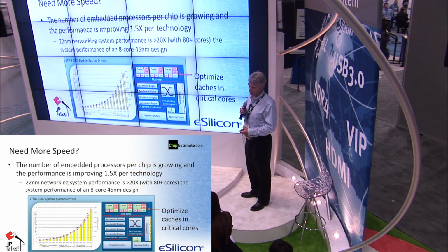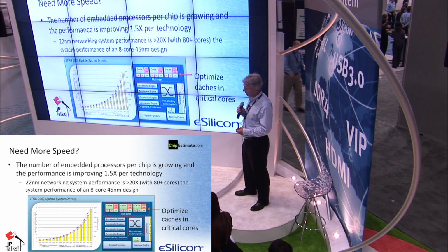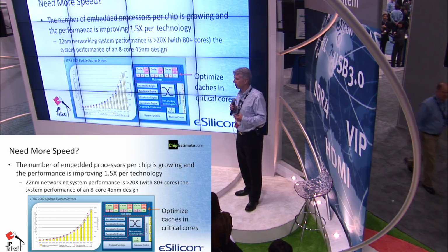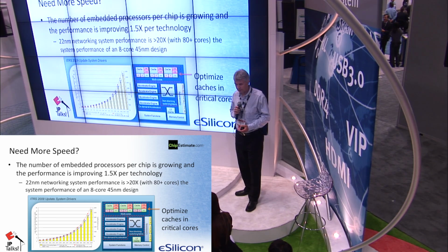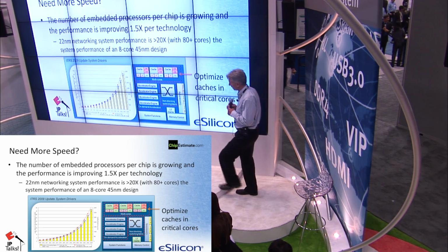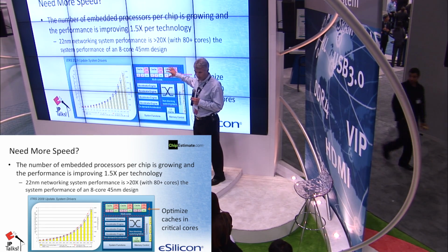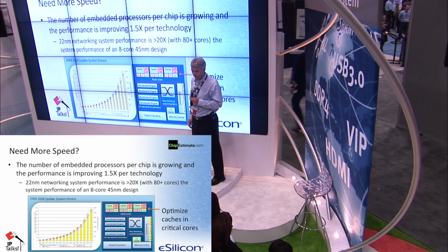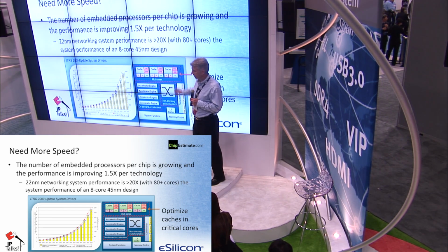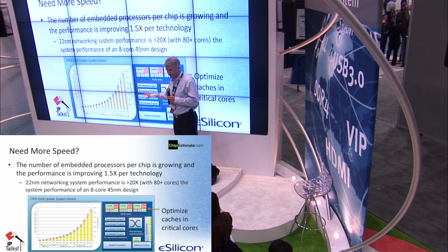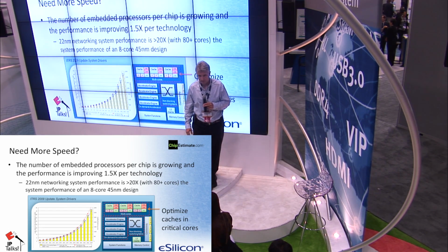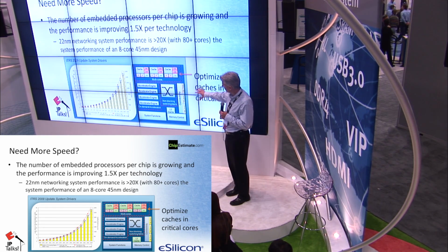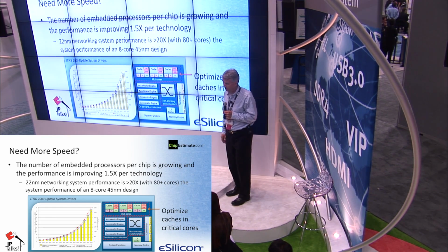Another thing that we find custom memory is very good for is speed. One of the things that's happening now in custom chip design, as I'm sure you're aware, is there is more and more processing going into these custom devices. In some cases, that's a multi-core. We're beginning to see the first quad-core designs coming out in phones. But it's not just the main core we're talking about here. In many cases, there are processing elements which you can think of as accelerators. And each of those requires some kind of access to cache or memory somewhere on the chip.